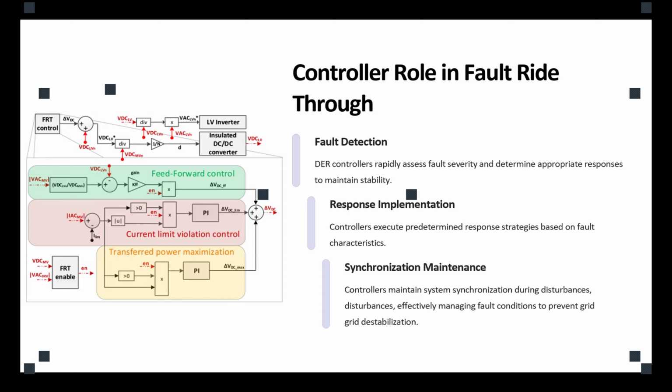Okay, so that being said, fault ride through situations are not inverters working regularly. They are going to respond to the fault, and they are going to have to increase their current or reactive power injection in order to answer to the fault and help the system to overcome the fault. What it means is that fault ride through makes the inverter not disconnect.